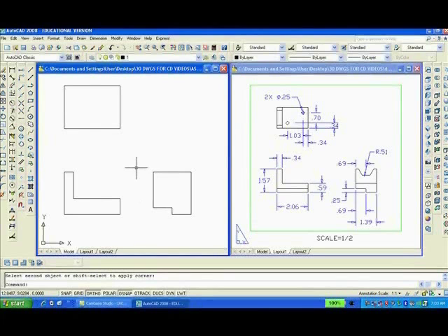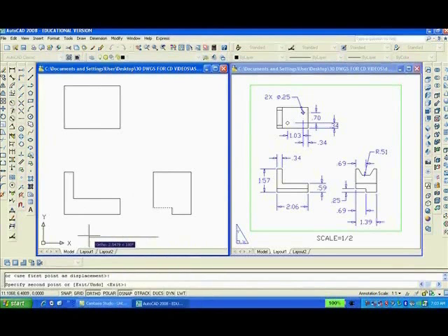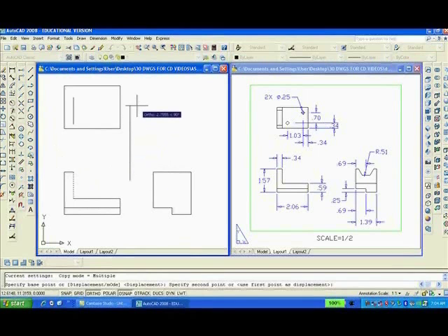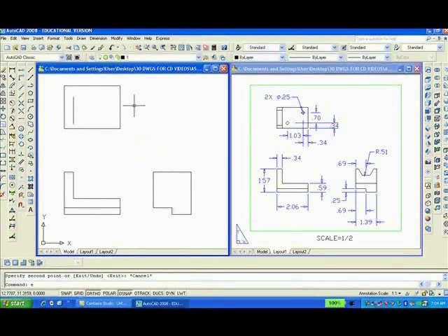Now you'll want to copy this line here. Escape or enter and extend, EX enter, to those lines, that. And we'll want to copy the vertical line and drag it up, and again extend to those lines, that one.